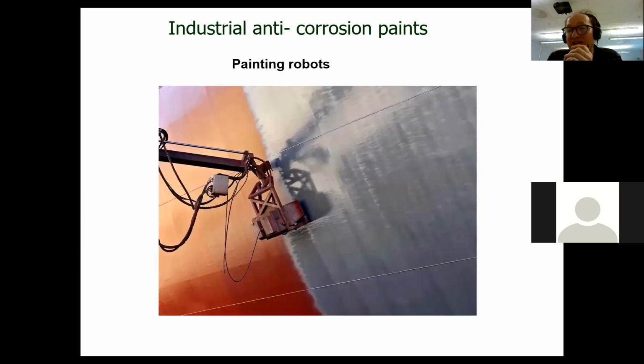Moving on, sometimes with a ship, we actually don't use people anymore to paint large ships. We use robots. And this is a very good example of where a robot works really, really well. Because going back to what I said before, part of the problem when you're applying a paint is getting the thickness just right. And if you're painting it by hand, you're almost bound to put more paint somewhere and not enough elsewhere. So you get a haphazard, random painting operation going on. And this you want to avoid. A robot is so much better than a human being for doing this job. So that's what we do these days. Generally, on a large object, like a big ocean-going vessel like this, you use a painting robot.